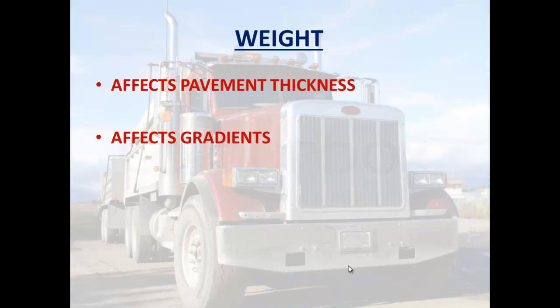In fact, the limited gradients are governed by both the weight and power of the heavy vehicles. Alright, so what needs to be done is that the weight needs to be standardized so that we can give gradients and the thickness of the pavement can be given in a feasible manner.